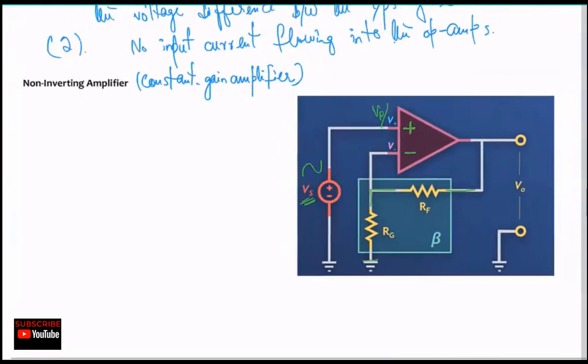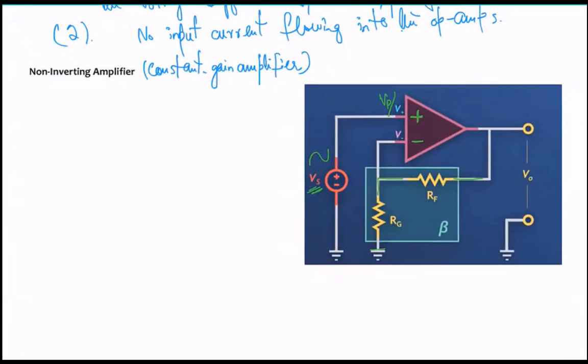Now if you remember, if we convert this circuit into a circuit model diagram, it gets a lot easier to apply nodal voltage analysis and KCL and KVL to get an equation for V naught and Vs. Basically, what we are striving for here is an equation for gain, which will be V naught over Vs, correct? So I'm going to start from the source, from this point.